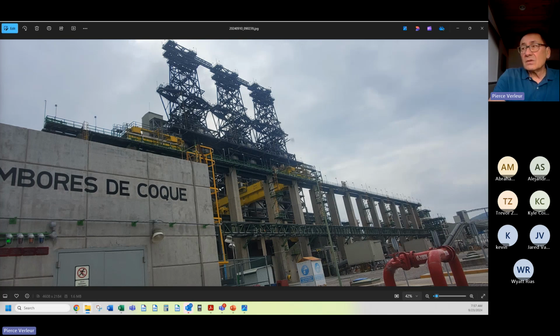It was 600 to 900 meters. And that just totally changed the whole characteristic of the tank circuit between the VFD and the motors. We're talking about lead lengths that we had no expectation of. We don't have a lot of time, so I'm going to short circuit this story.